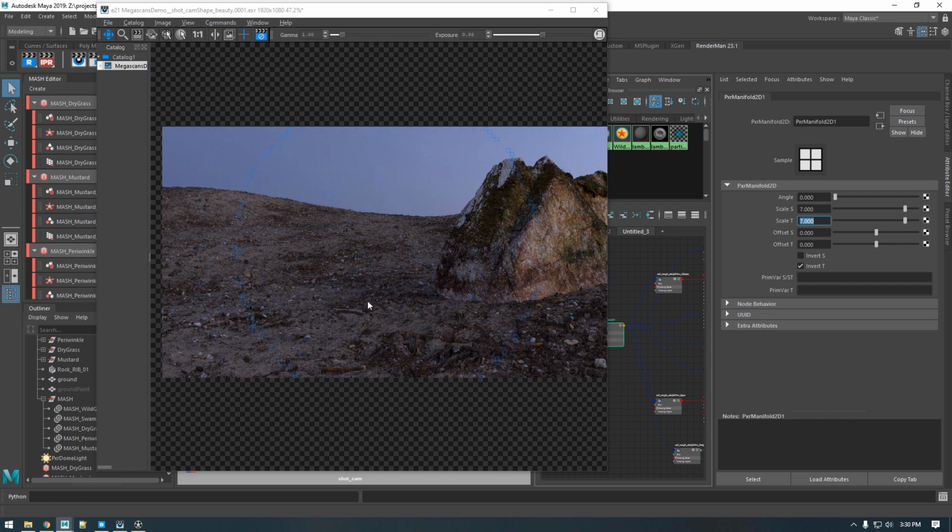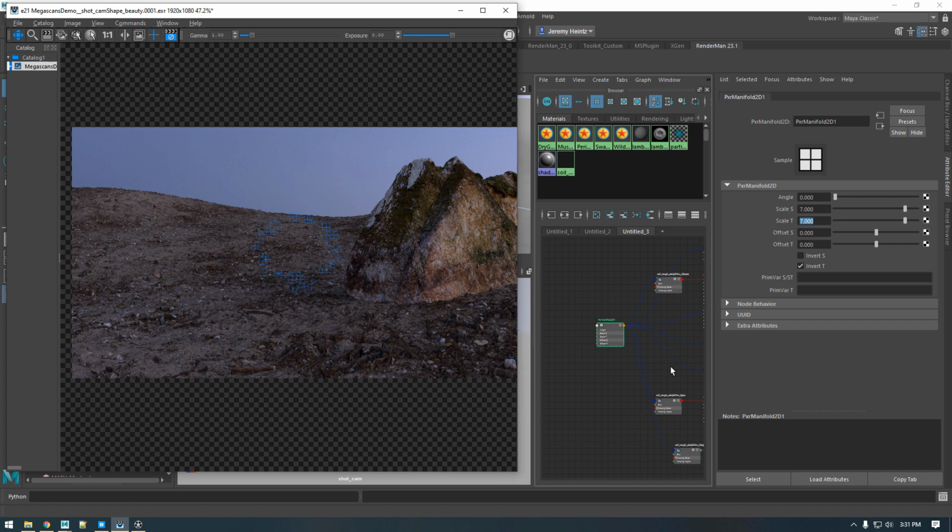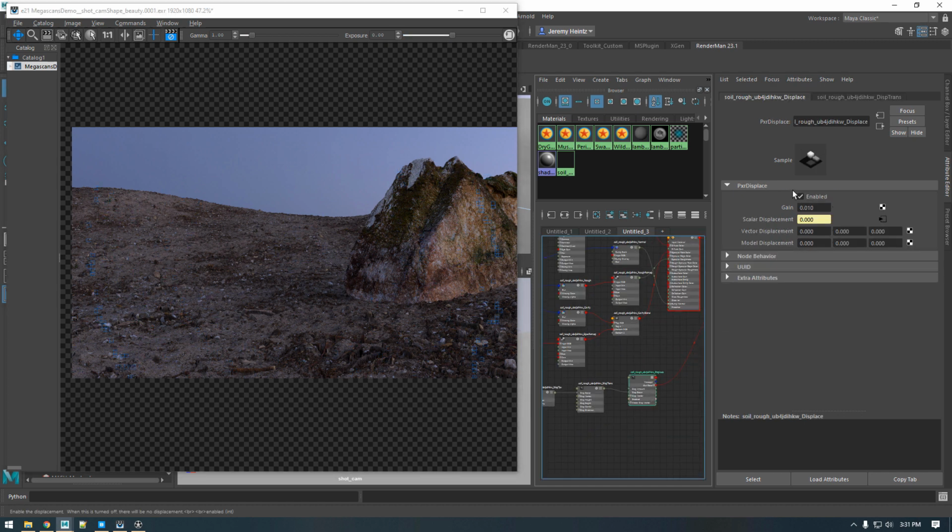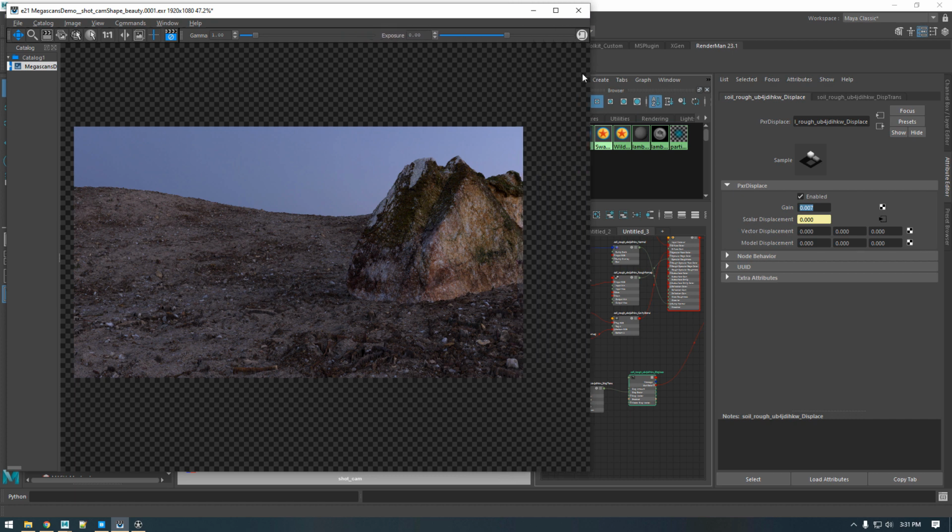I'm not picking up any real texture repetitions visually, so I'm going to go back in and adjust the displacement amount from 0.01 to 0.007, just to tone it down a little bit. It's a little steep. I'm going to pause this while it recalculates the displacement. Alright, so starting to sample. It still might be a little much, but I'm going to leave it.